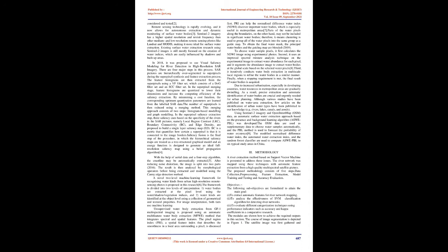An innovative method for retrieving information on storage fluctuations in any inaccessible place using Landsat data and digital elevation models, DEMs. The method, unlike other systems, does not require any in-situ measurements and is suitable for monitoring tiny, often undocumented irrigation reservoirs. It comprises three steps towards recovery: 1. A 2D dynamic classification of Landsat spectral band information to estimate water surface area. 2. A 3D reconstruction approach to account for clouds and the Landsat 7 scan line corrector failure, and 3. A statistical correction of DEM data to represent reservoir topography.